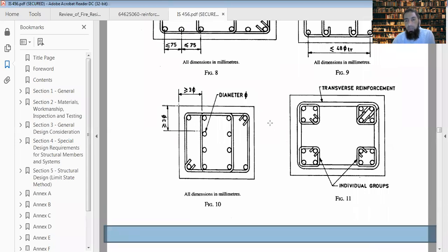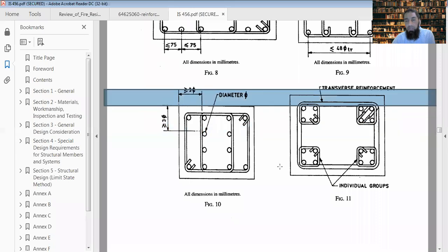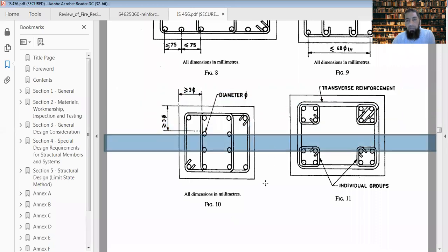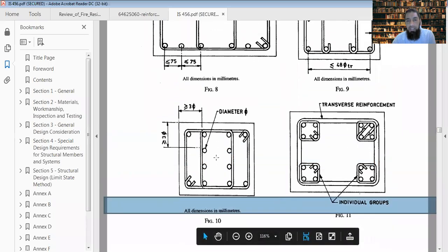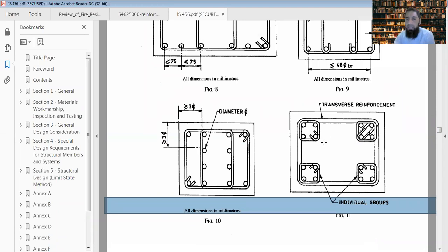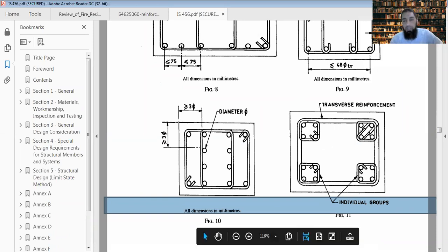If you have a large load and a big column, then this is done. Usually, no longitudinal reinforcement is provided at the center. You will see that the center portion is usually kept open. And this is again done for compaction purposes such that the compaction happens properly.